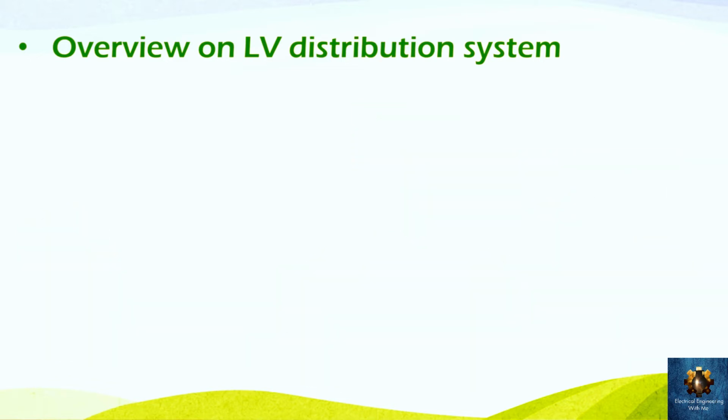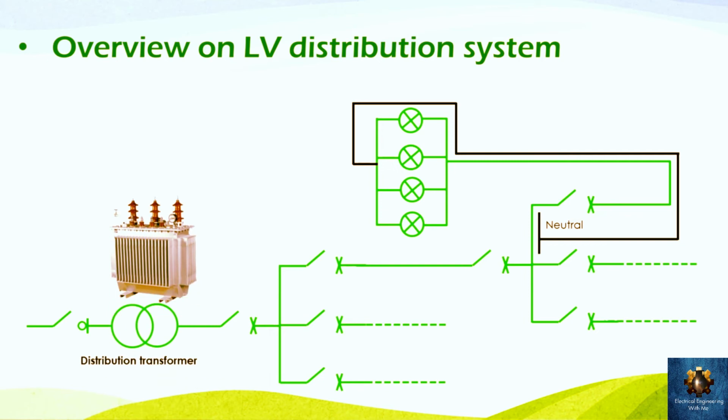After that, the second component we have is the transformer, and the job of the transformer is to convert the input power from the medium voltage level to the low voltage level, as the electrical loads work at a voltage rating equal to the low voltage level. Hence, we use this transformer to decrease the input power from about 11 or 22 kilovolts to only 400 volts.